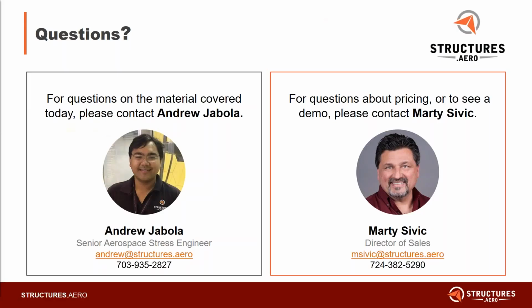Another question that I saw came in from, in this case, someone at Siemens, is, are grid point forces for random analysis available? And if so, are they of any use for the Femap free body display? The problem with the data shown here is that this is an RMS value. So you're actually seeing what could be the potentially max value of the system, but it may not occur at the same time another max value occurs.